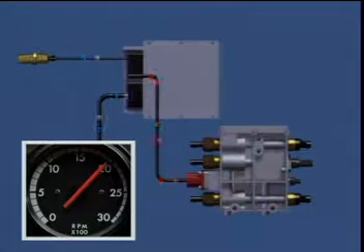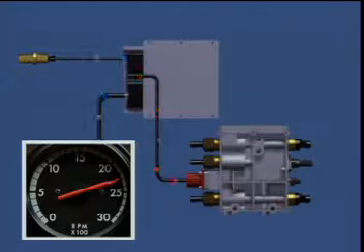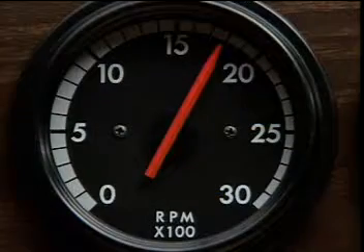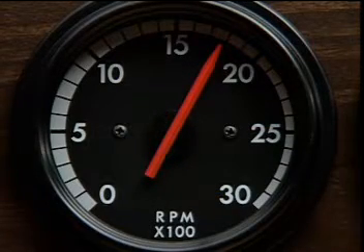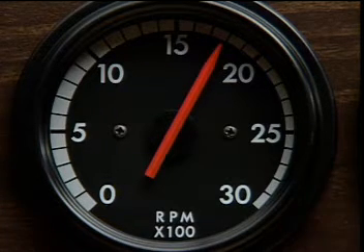The overspeed protection feature monitors the engine speed and shuts off fuel to the engine if an overspeed condition is detected. The engine speed at which an overspeed condition is detected depends on the calibration. A fault is logged, and the ECM records engine data when the fault occurs. Fuel flow is restored to the engine when the engine speed drops below a secondary engine speed threshold.